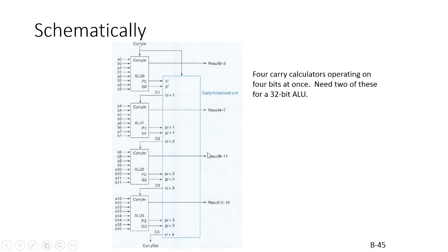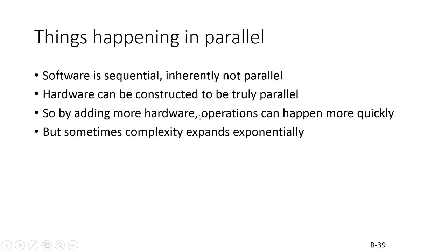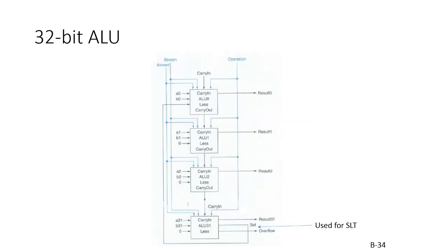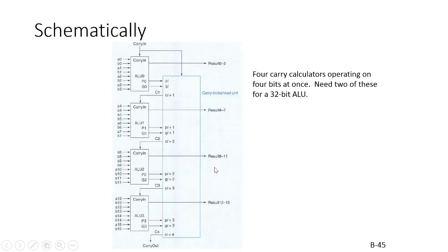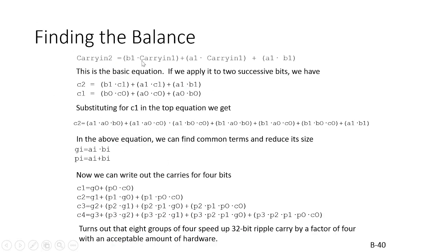There's always going to be addition occurring. I mean, that's fundamental to computer assembly and organization. And so building a carry look-ahead unit allows that addition to take place simultaneously without having to do a ripple, like I taught you guys about here, where we just slowly carry the 1 bit at a time. Instead, a carry look-ahead unit deals with each of these functions by creating Boolean arithmetic for each of the carries.